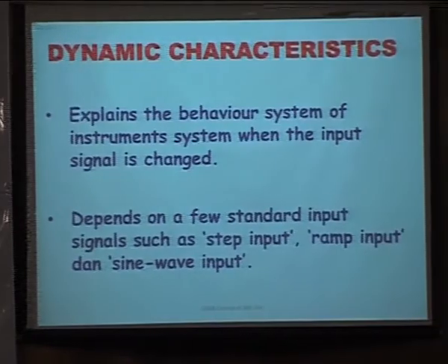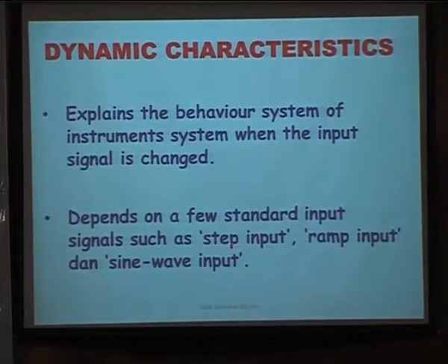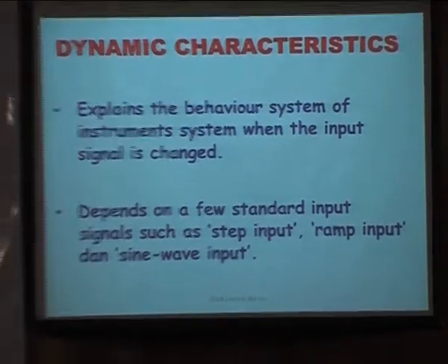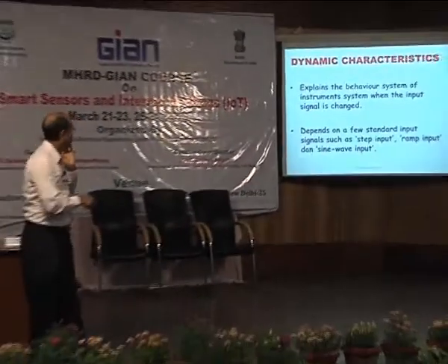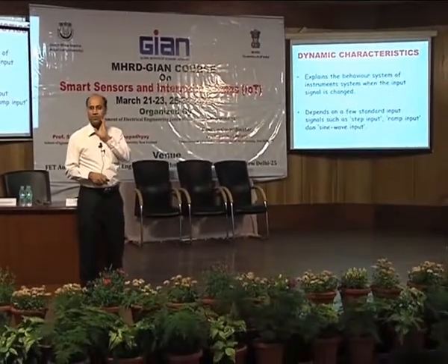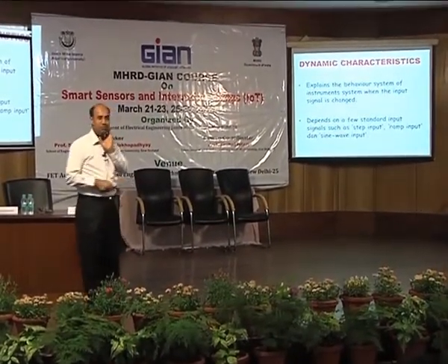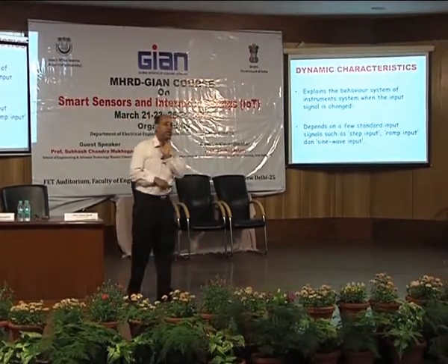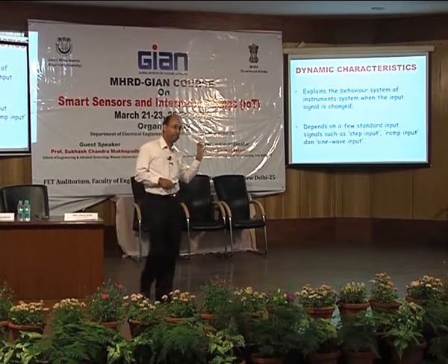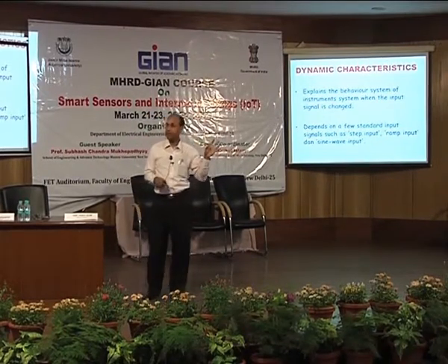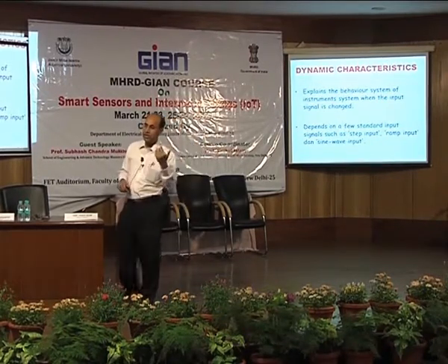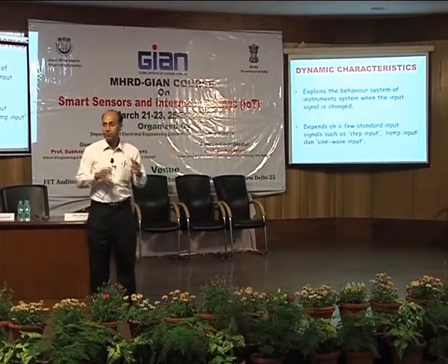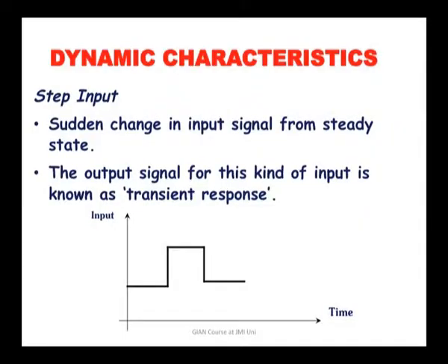The reference inputs which are used: one very common is the step input. Step input is the most commonly used, and sometimes the ramp input, okay? There is another input, the acceleration input, but that's not so common. And you can also use a reference sine wave. The reference sine wave can be very useful. It's not for the response time, but for the phase delay. So it's the frequency response analysis which is useful.